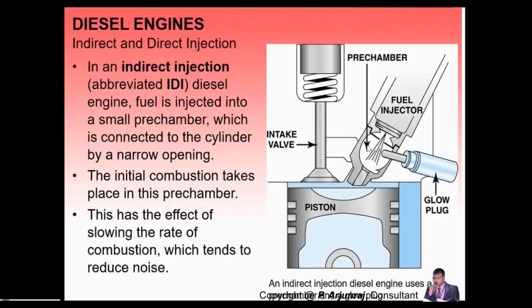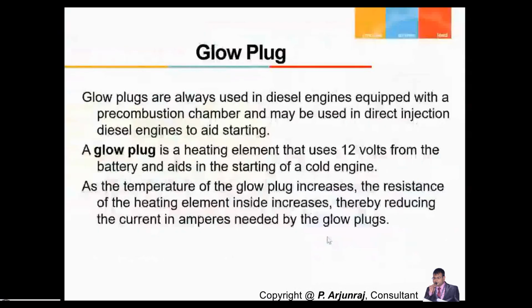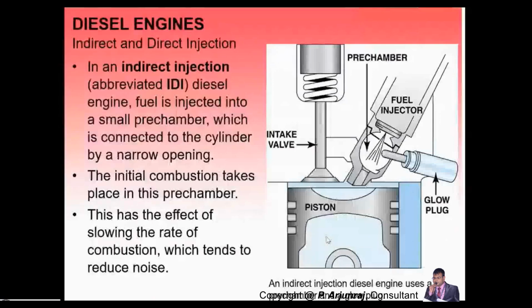Okay? And if the combustion happens at the first stage, and then the same combustion passes through this opening, and the final combustion happens above the piston and in the combustion chamber, then you tend to have less noise. That's also one of the advantages, because the pressure and the temperature would otherwise be higher, and that will cause higher noise because of a diesel.